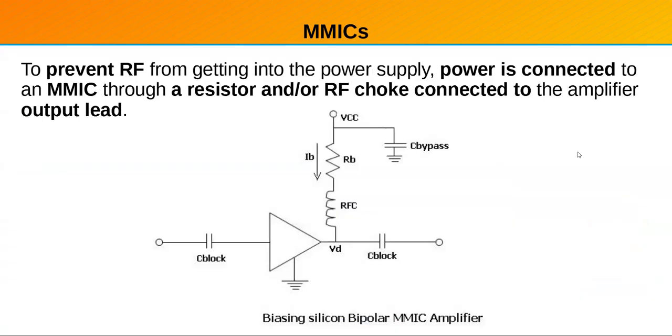Okay, so the way you hook these up, and they're kind of oddball in that you supply power to the output. It's basically an open collector or open drain type of device.